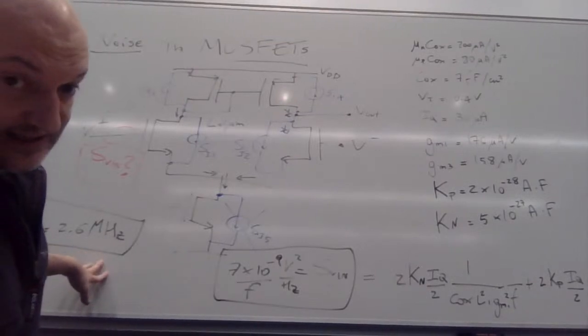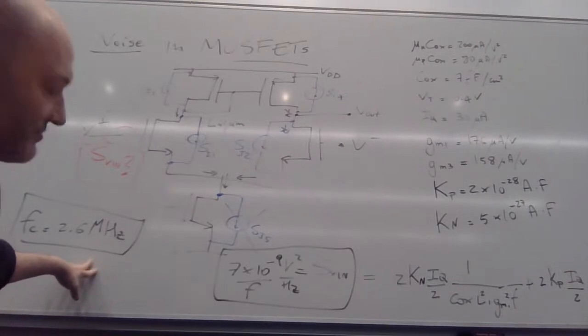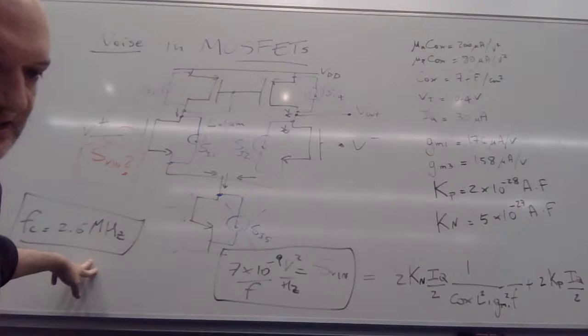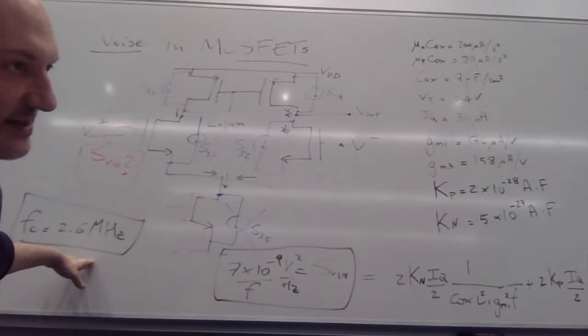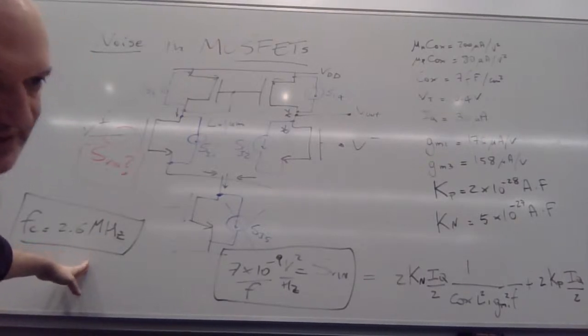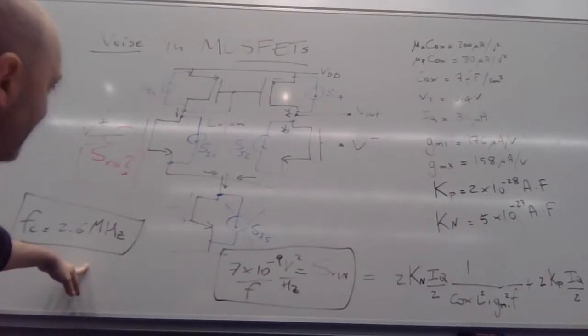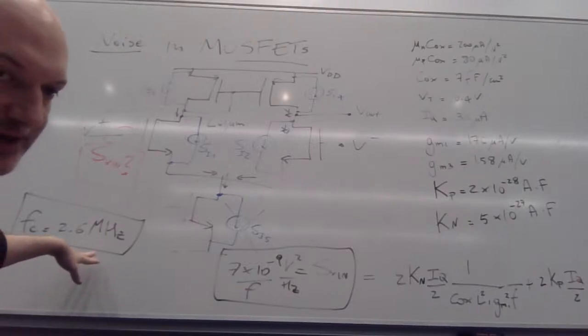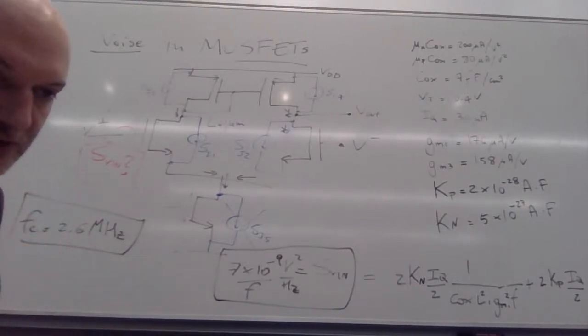Okay, and this one is a bit of a problem because CMOS operational amplifiers, for this reason, have a considerably higher noise than other types of technology. For example, if you use a power technology, the noise is considerably lower. Likewise, you can combine CMOS, what's called a BiCMOS technology, and again, in that case, you can exploit the low noise of the bipolar transistors to get a considerably lower corner frequency.